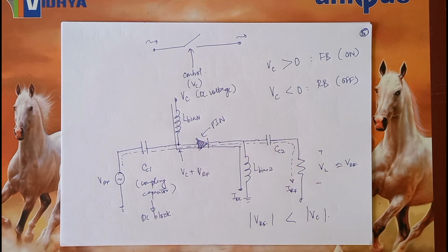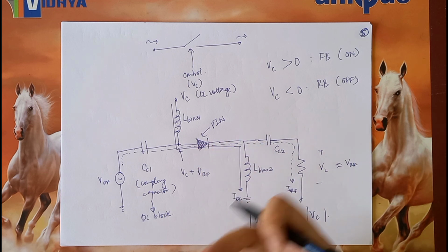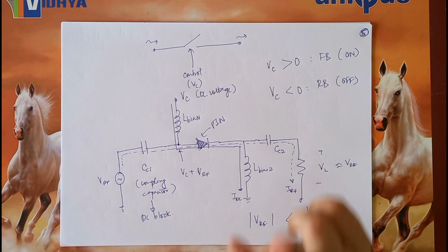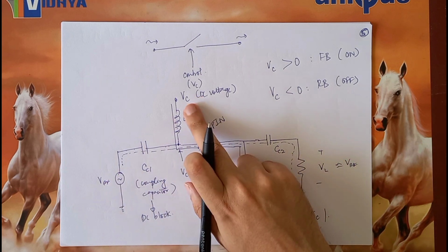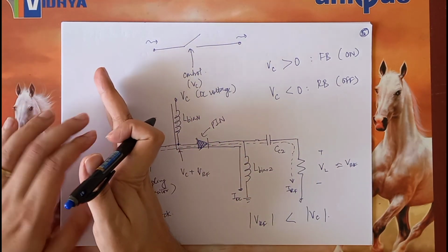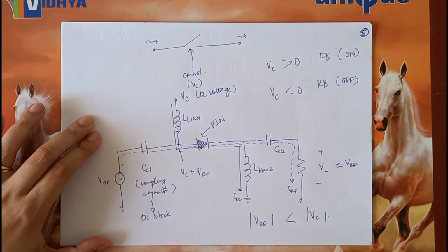So it has a smaller capacitance, which makes it act like a better reverse biased off-state diode. Therefore, this can be used as a good switch. But do not forget, the switch has to be powered or operated through an additional control voltage. It is the question of whether the entire RF signal is sent from one point to another point.